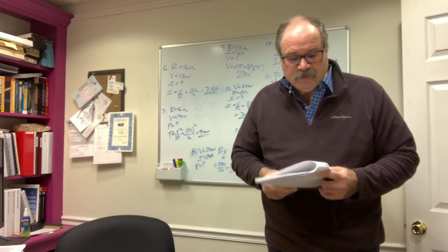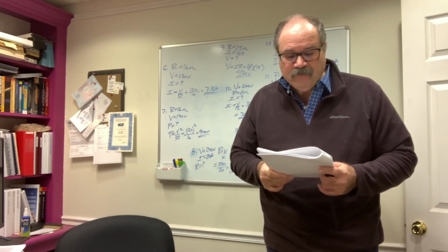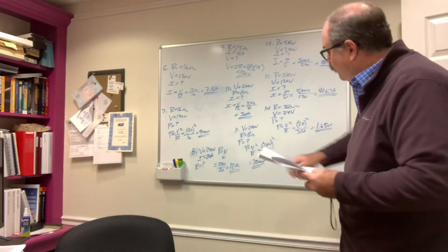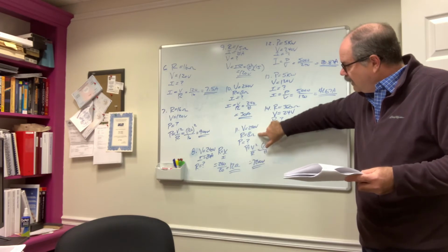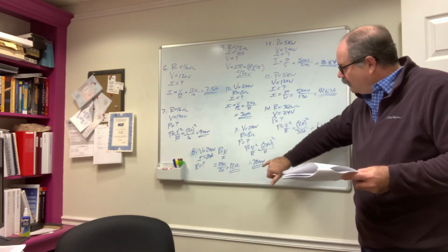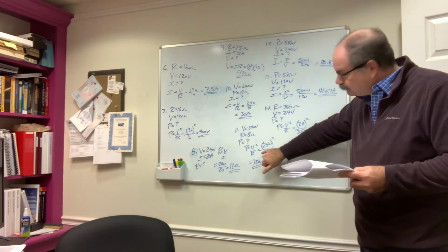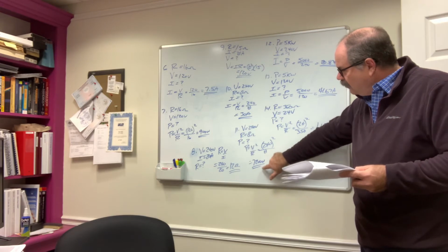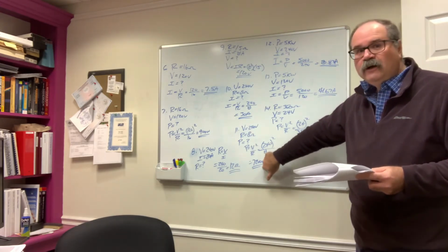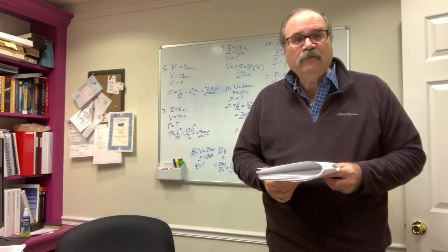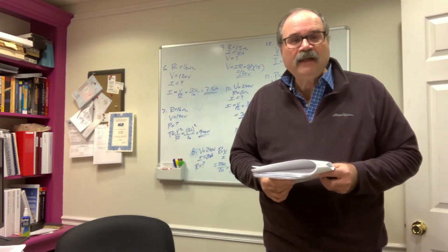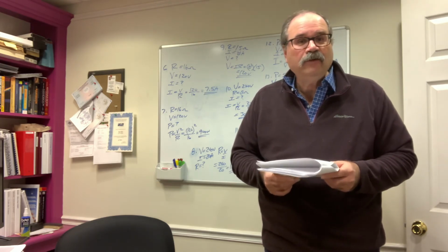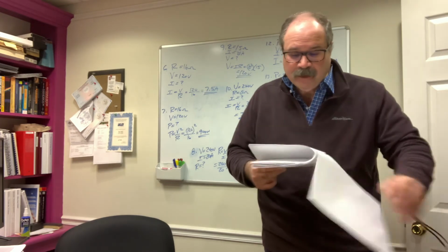Question 11. How much power is being used by a compressor if it is connected to a 240 volt supply and has an apparent resistance of 8 ohms? 240 volts, 8 ohm resistance. Solve for the power. Power is equal to V squared divided by R. Plug the numbers in. 240 volts squared divided by 8 will give us a power of 7,200 watts. Should also point out, using engineering or scientific notation, 7,200 watts can also be specified as 7.2 kW, and it's very commonly done.